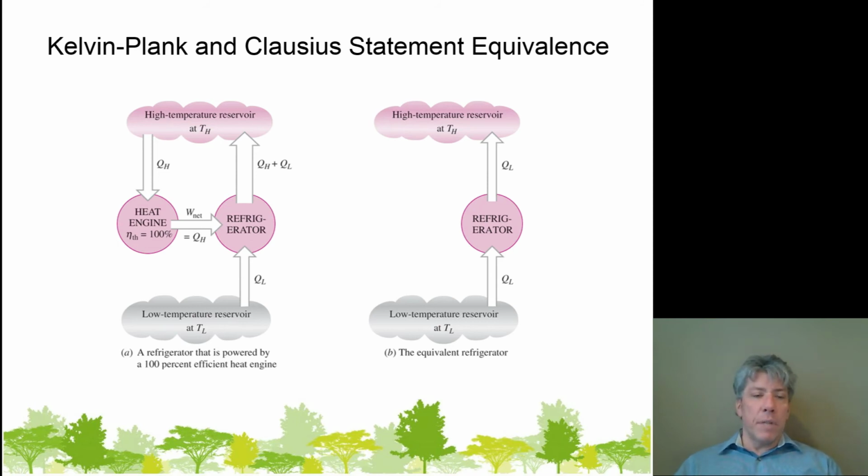But the heat engine, the Kelvin-Planck statement that you can't just take in heat and convert it all to work, you probably in the back of your mind thought, I wonder, is there a way to do it? Well, if you believe the Clausius statement, you have to believe the Kelvin-Planck statement. They are the same thing. There is no difference between the two. The logic leads you to the idea that they are equivalent statements of the second law. So if you believe heat won't flow from cold to hot with any device you were to build, and a lot of people have tried, then you also believe that you can't take heat and convert it all to work. Some of it has to be thrown away, and that's a very important result to obtain.